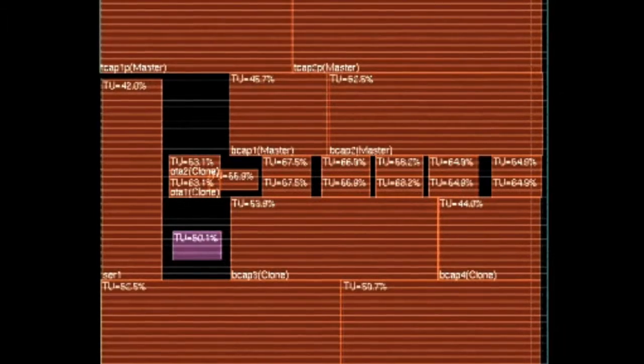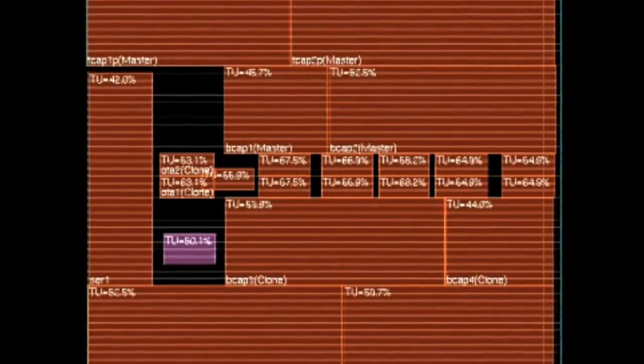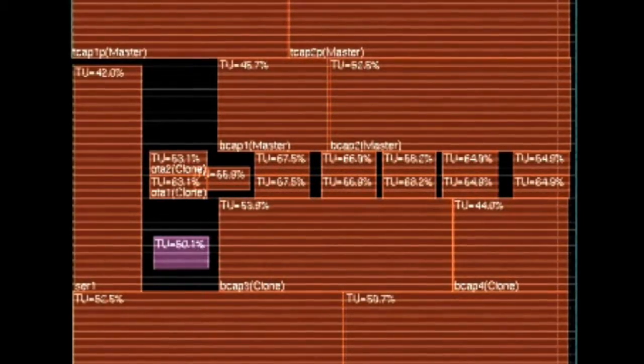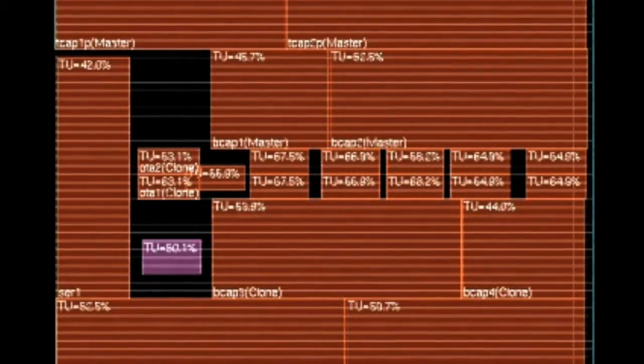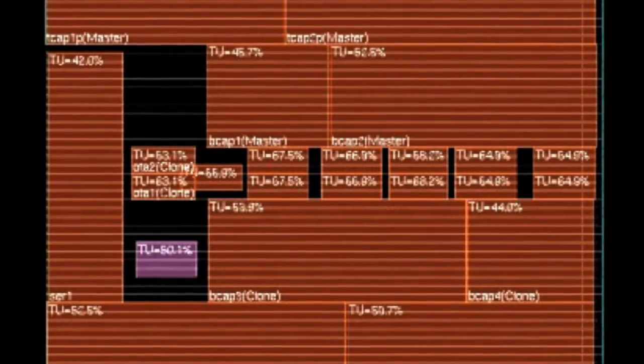Each box in this floor plan diagram constrains the placement of the major modules within the top level HDL design. Critical areas of the circuit, such as the TCAs, are constrained close together around the center of the die, whereas less critical circuit components, such as the trim capacitors, are constrained on the outer edges of the die. Notice the symmetry around the center horizontal line. That provides the symmetry for the differential signal paths.